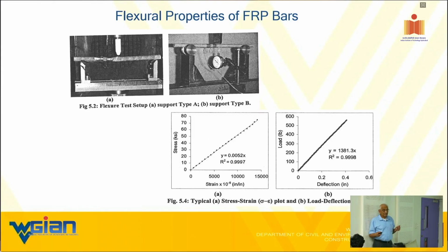So I'll give you another way. I never said this, I should. I forgot really. Compatibility in terms of stiffness of FRP to concrete is fantastic. Why? They're all about 3 to 4, 5 MSI range, whereas the steel is 6 times stiffer than concrete. 30 million is steel. Concrete is about 4.5 million PSI for recent concretes, not the old ones.